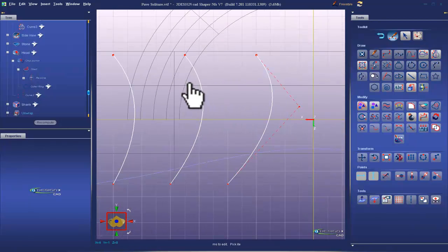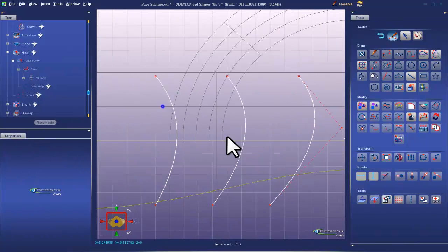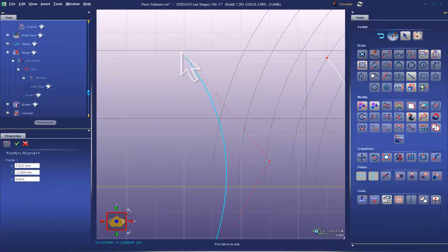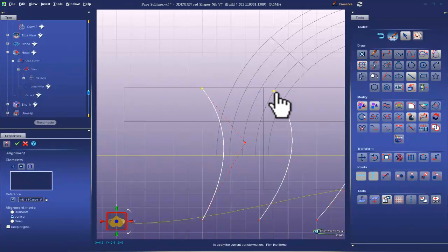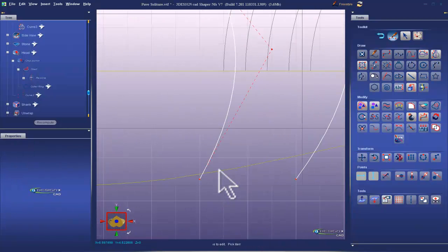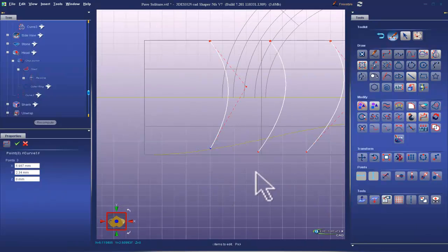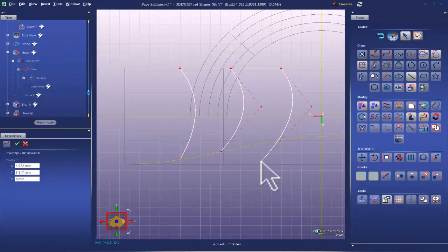Let me see. I'm going to turn my grid snaps off. Validate. I'm going to bring this up just inside here. And then I'm going to do an alignment. I think it's vertical. I'll tell you in a second. Nope, it will be horizontal. Like so. Validate. And then this one needs to come inside the yellow line. These I have to do all by eyeball. The reason I offset is because I wanted that 0.8 millimeters of purchase. That'll make a lot of sense in a second.